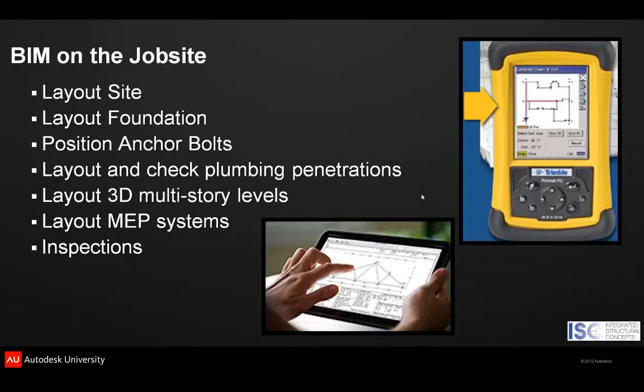A tremendous amount of money and energy has been spent to integrate BIM with the job site. Companies such as Trimble and Leica have developed technology that allows BIM models to be imported into robotic total stations in order to lay out critical path items. GPS devices can integrate with optical devices, and the intelligence is hardwired to allow multiple users with the same technology on the site without interference. Tablet-based computing will provide a myriad of uses in the field.